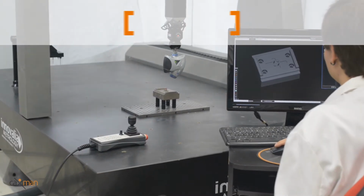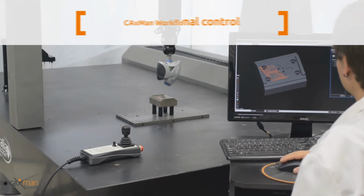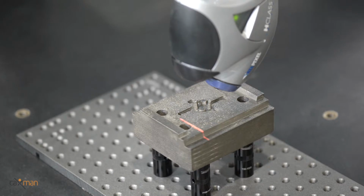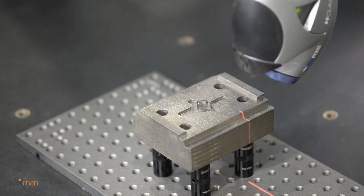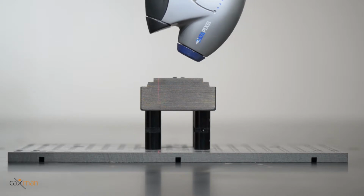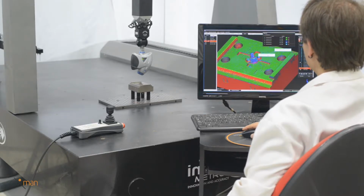The dimensional control step is done by Trimec, a leading company in the Spanish market in the field of coordinate measuring machines and measuring and digitalization software. After printing, the parts are 3D scanned to check that the additive manufacturing process has produced a compliant part. After the parts are milled to obtain the required smoothness and precision, they are scanned a second time to check that the geometrical and dimensional tolerances prescribed in the design phase are fulfilled.